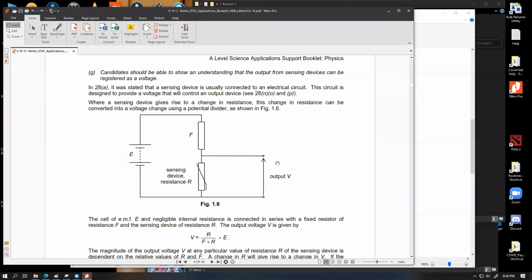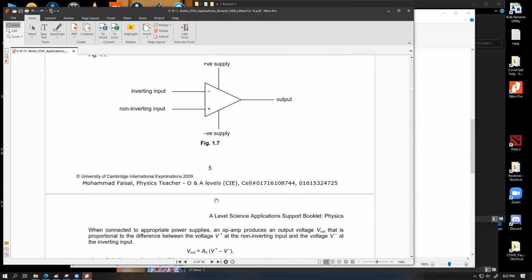and if we calibrate this device with appropriate measurement of that physical variable, if you're using a thermistor, then the physical variable is temperature. If you use an LDR, the physical variable is the light intensity. If this voltage is calibrated for some known values, by observing the voltage, we could reciprocate back and have an absolute reading of what the actual temperature of this device is. So that's what they're saying, that by measuring this properly with a sensitive enough analog or digital device, and if that device is properly calibrated, it is possible for us to understand what the exact value of the physical variable is at this place.